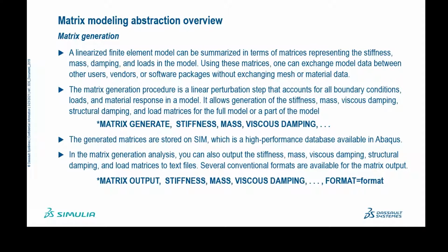And then the keyword here is *MATRIX GENERATE, with stiffness, mass, viscous damping, structural damping, or load, depending on the case. So the generated matrices are stored on the SIM file, which is a high-performance database available on the Abaqus run directory.